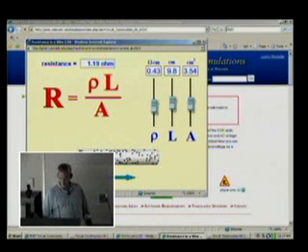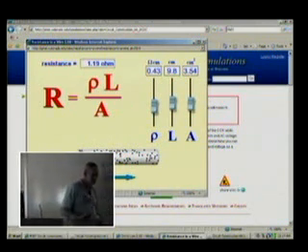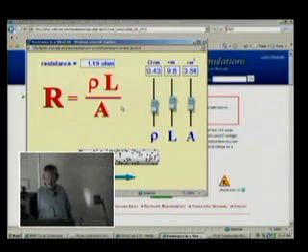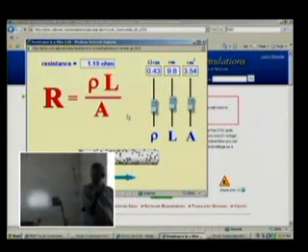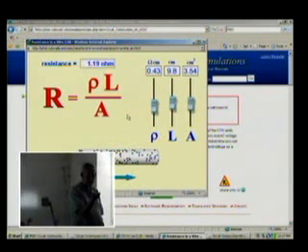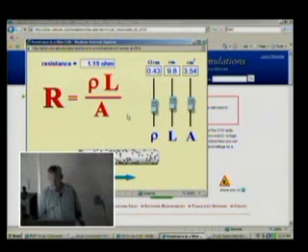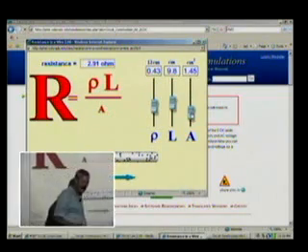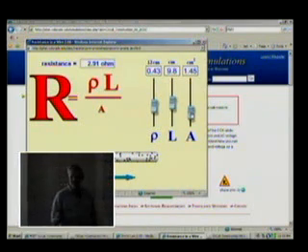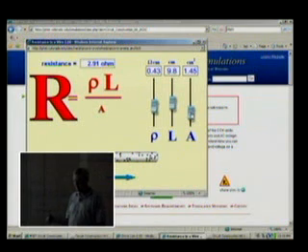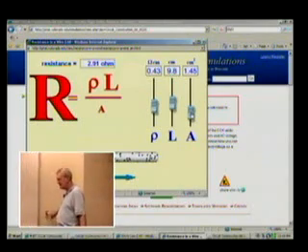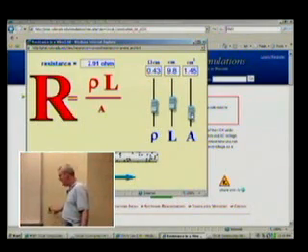So anyway, if the resistance is high, just like in a mosh pit, it gets hot. Things get hot. And so if you've got a really thin gauge wire that needs a lot of amps hooked up to a space heater, and you've got a real thin extension cord, look what happens. Because it's got low area, the resistance goes up. It gets very, very hot. That's why those small extension cords are dangerous with space heaters, because they'll eventually melt the plastic insulator on the outside of it and then start a fire. So there you go. Got that part done. Now we'll turn that off. We'll go back to that here in a minute, too.